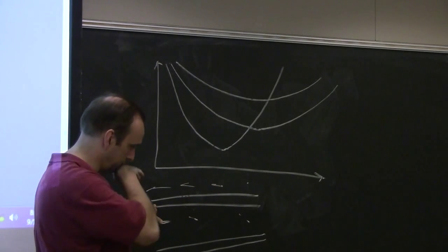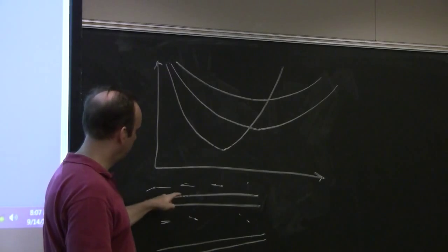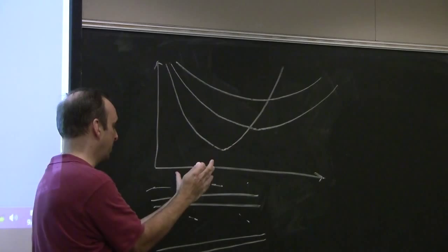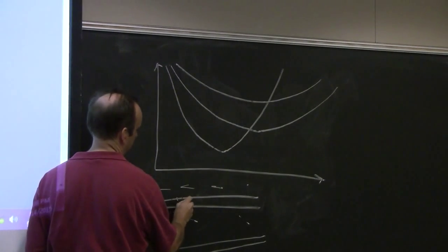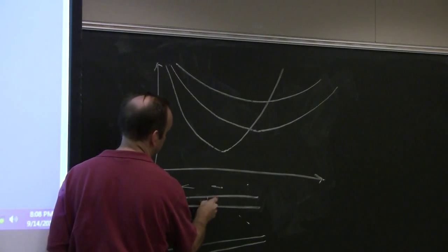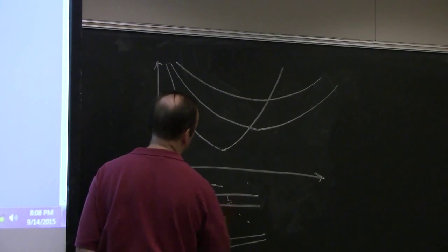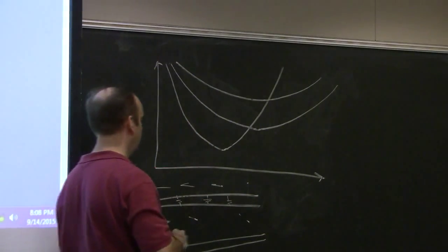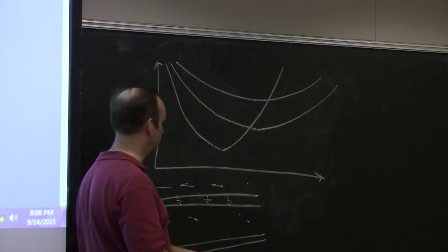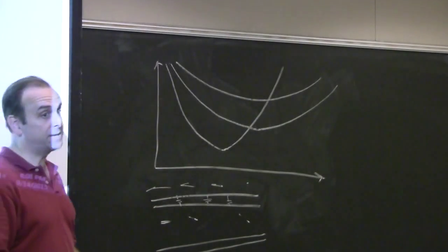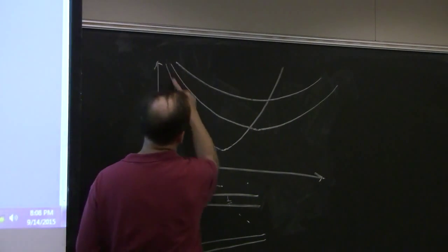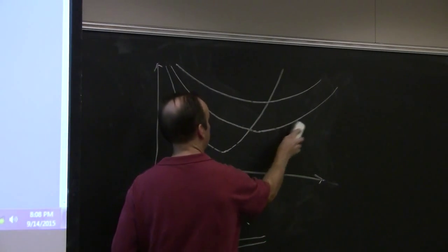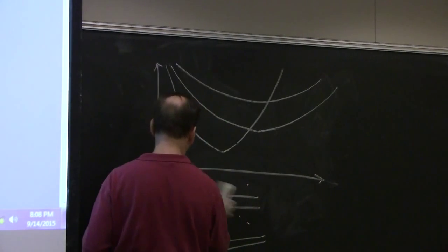I mean, this is a relatively large pair of metal conductors placed pretty darn closely together. They're only a few thousandths of an inch apart. This becomes a capacitor. And this actually is the best capacitor on the board. This is your best high-frequency capacitance. And it's not because of a capacitor placed on the board, it's an intrinsic function of the geometry of the board. So yes, capacitance absolutely makes a difference. And this idea that capacitor just goes out like that is not true. And the faster you go, the farther you get out to the right, the more you realize that's true.